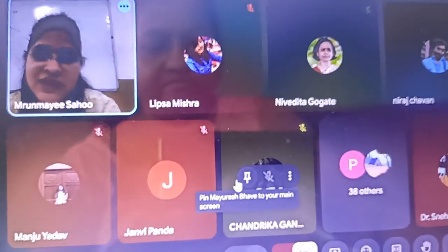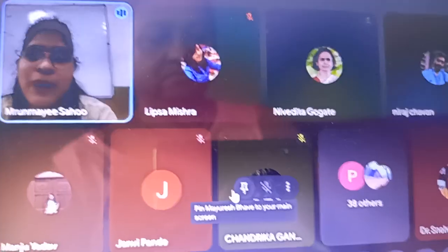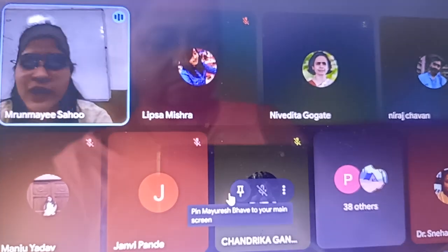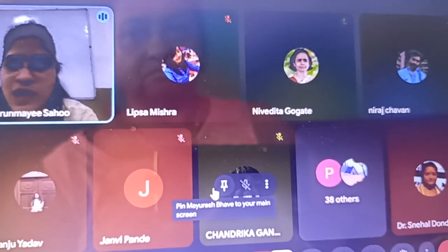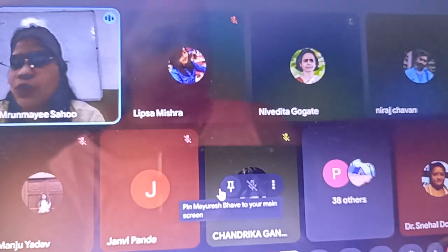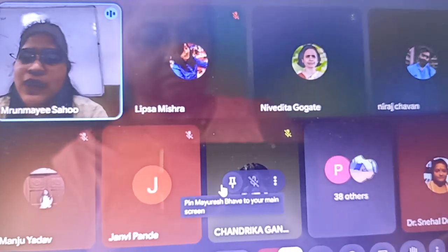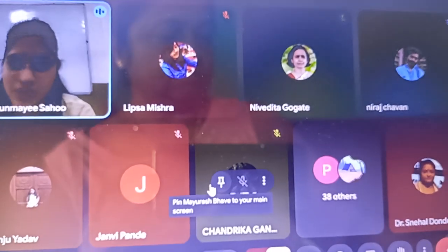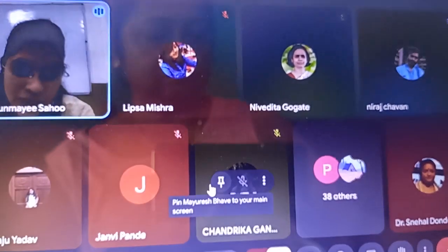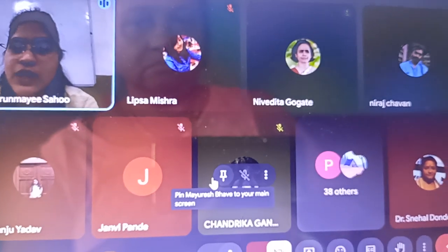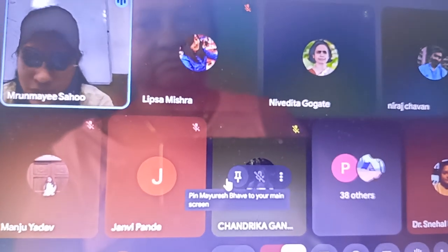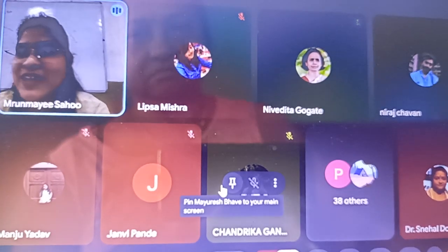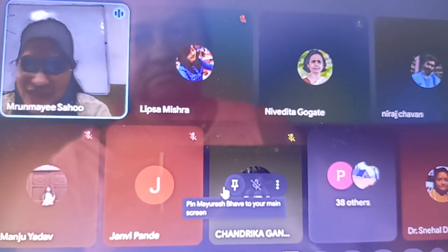Yeah, actually, one of the pilot studies which I was discussing was already implemented in part of Jalandhar. We have an MOU with PWSSB, which is Punjab Water Supply and Sewerage Board, and with the MOU we have implemented one pilot study. Earlier NRW was 30%, and now we have reduced it to 15%. It should not be like we overestimate that it will be reduced to 0%. It cannot be reduced to 0%.